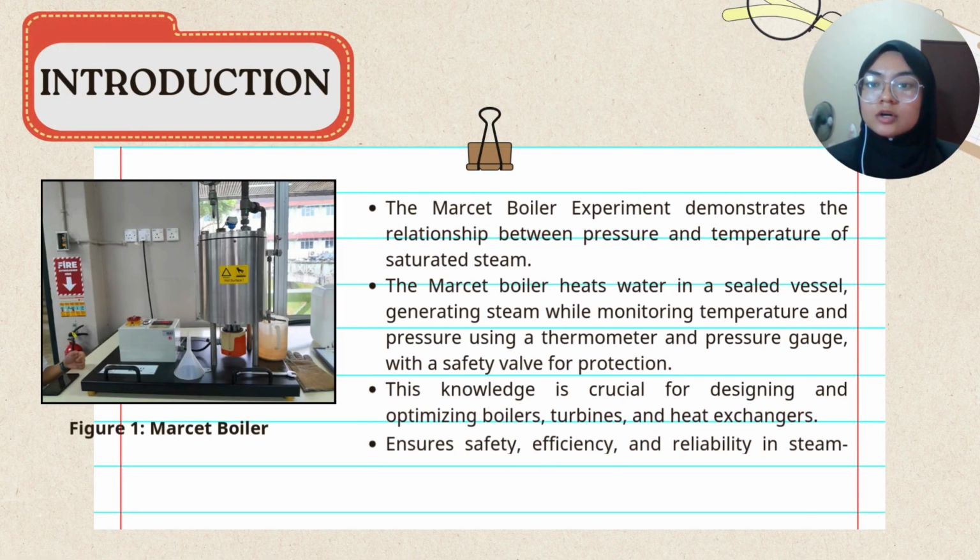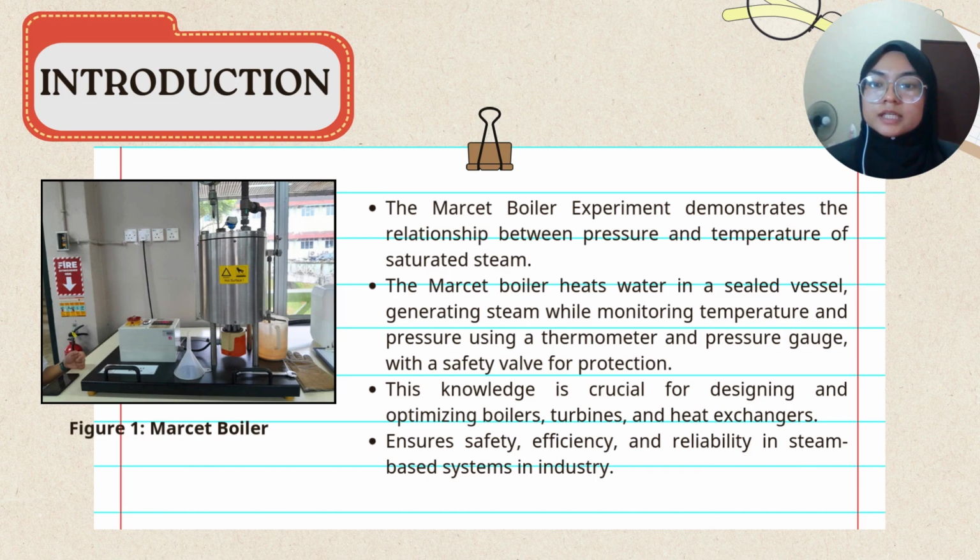For the introduction of the Marcet Boiler experiment, this experiment demonstrates the relationship between the pressure and the temperature of the saturated steam. So this is what we call thermodynamics. This is also essential for designing and operating steam-based systems like boilers, turbines, and heat exchangers in industries such as power generation, chemical processing, and also oil and gas.